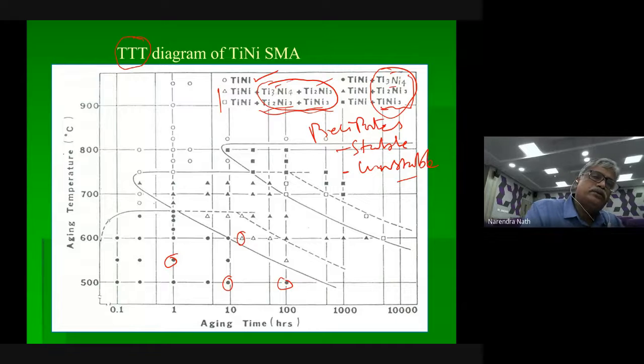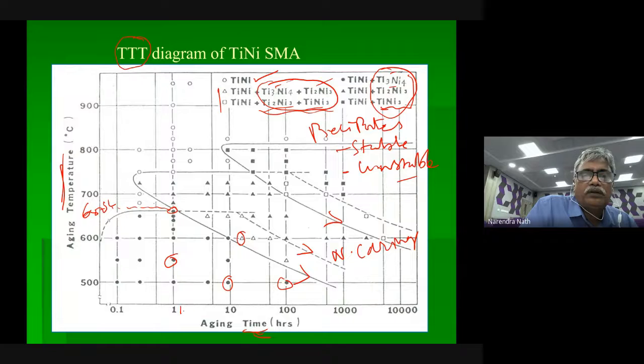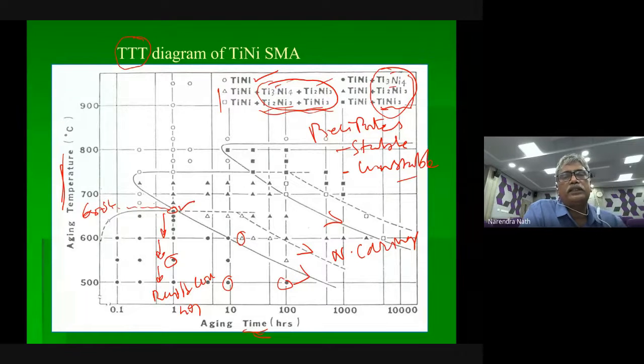For that, you have to use this temperature versus time during aging after melting. This is actually natural cooling. You see all these are natural cooling. But suppose at this point it is around, say, 680, and I want this phase, with a timing of 1 hour. What I can do is rapid cooling. When I do rapid cooling, this phase, whatever is existing, is arrested and stays there.